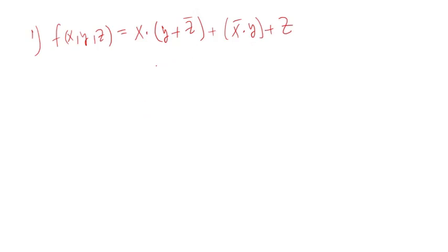So the way I would approach it, you take one term and start from there. For instance, I'm going to take an AND. This operator here is an AND, so I'm going to draw an AND gate, and it has an x. Then I see that I have an OR gate, which is an input to this AND.